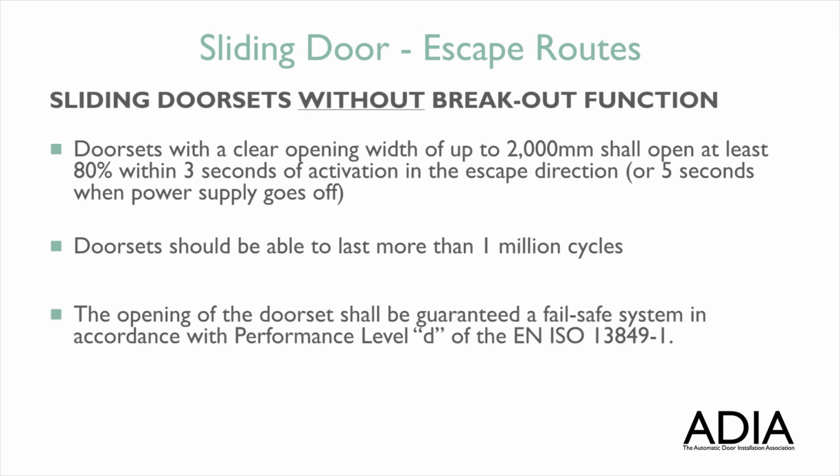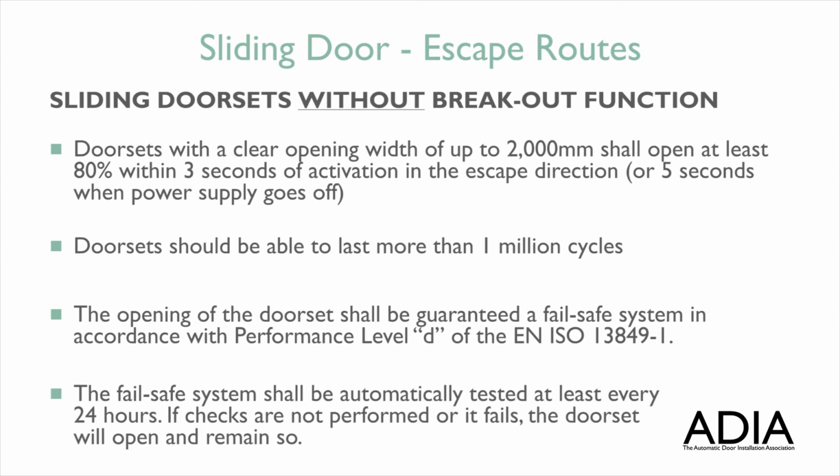The opening of the door set shall be guaranteed a fail-safe system in accordance with Performance Level D of the EN ISO 13849-1. The fail-safe system shall be automatically tested at least every 24 hours. If checks are not performed or if it fails, the door set will open and remain so.